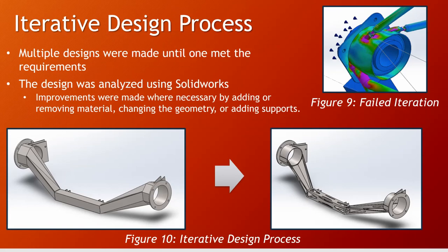There are over 10 versions of this beam that were created in order to make a satisfactory suspension. Through the second truss style beam, it was shown that by distributing the stresses to more members, it is possible to decrease stress concentrations. This distribution of loading to larger areas also decreases the weight of the beam at the same time. More of the material is stressed rather than in the original beam that has huge areas with very low stress. Essentially, it has large amounts of wasted material. The truss style is a more effective use of the material that needs further study before it is constructed for use on the car at competition.